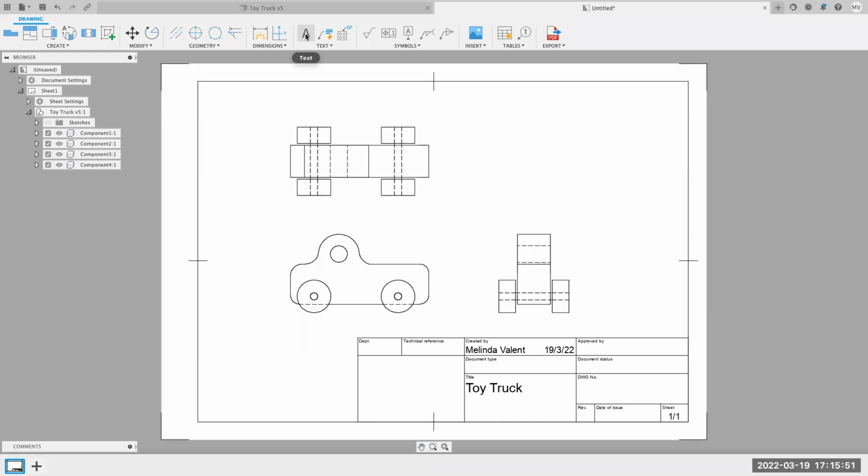So on your orthogonal view, you've got your views now. You've got your 3 views. You need to label these. This first one, just creating a text box, is the front view. Okay. The front view is the one that gives us the most information, and always sits below the top view and to the side of any side view, of course.